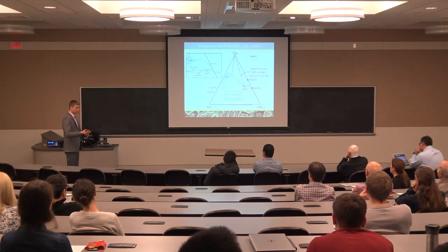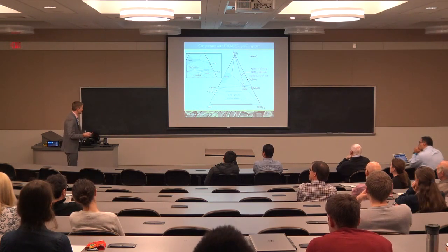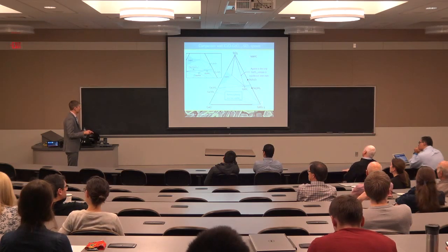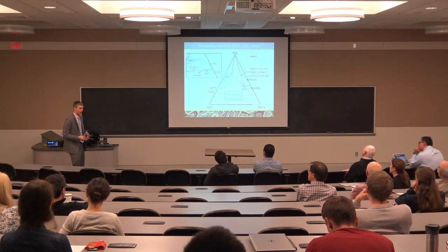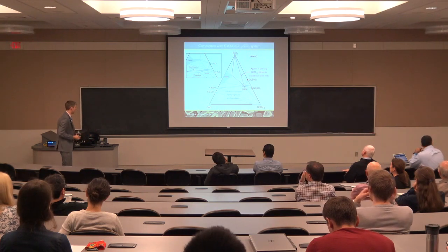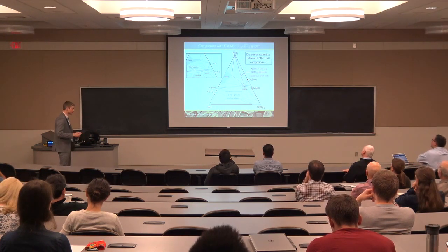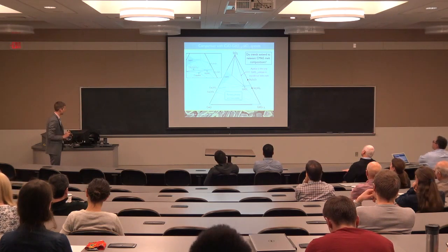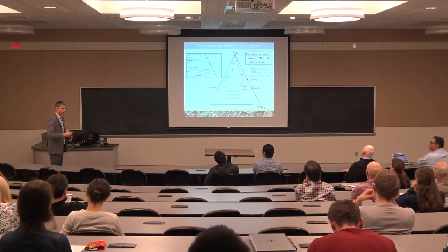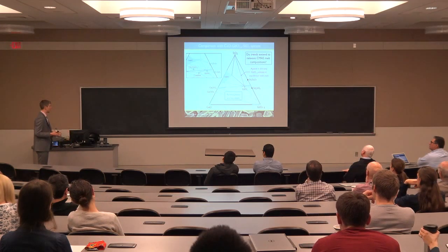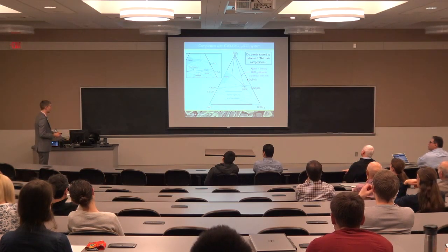But if our goal is to promote apatite crystallization, as it is in the case of the thermal barrier coatings, gadolinium would probably be a better choice because of a stronger driving force for apatite. So the next question is, here we're looking at a ternary system. Does this actually extend to relevant CMAS compositions or the relevant deposit compositions for the application?